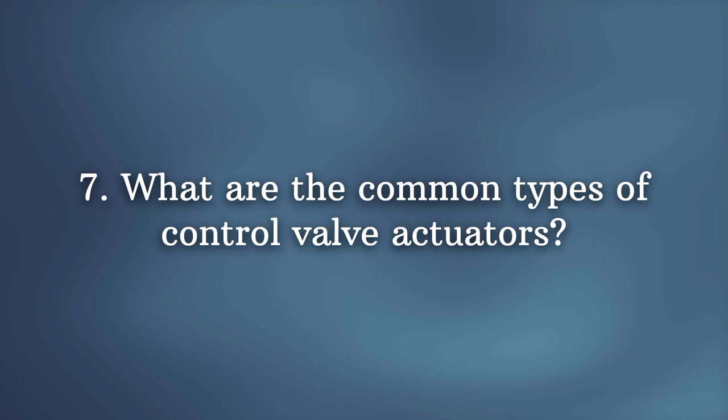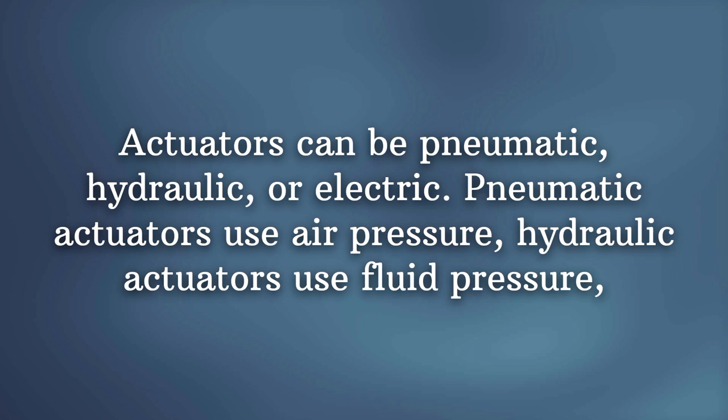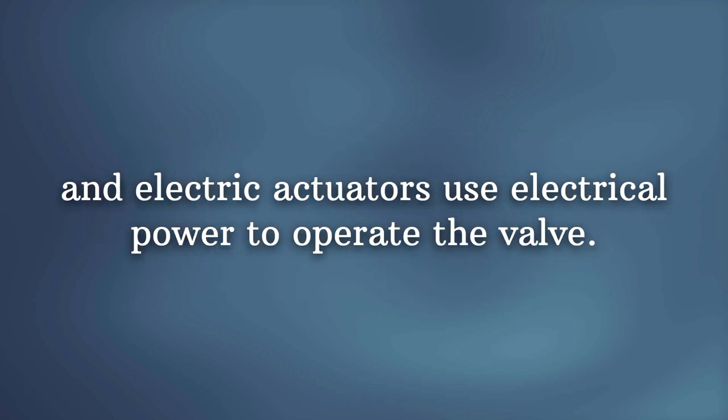What are the common types of control valve actuators? Actuators can be pneumatic, hydraulic, or electric. Pneumatic actuators use air pressure, hydraulic actuators use fluid pressure, and electric actuators use electrical power to operate the valve.